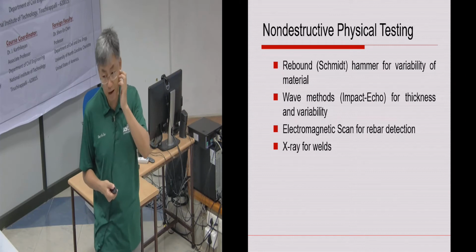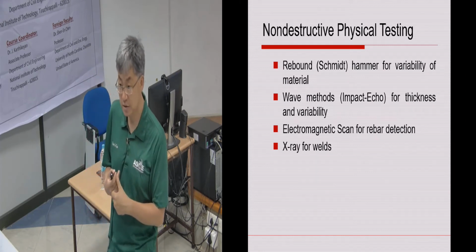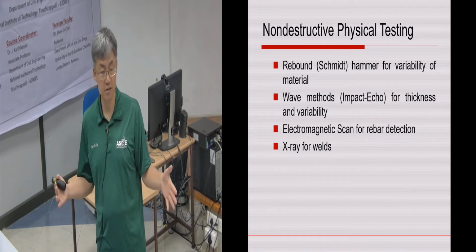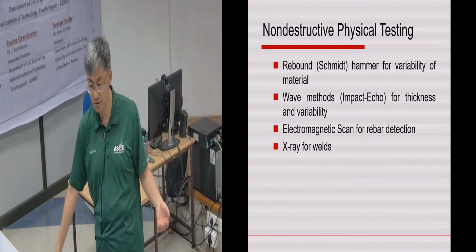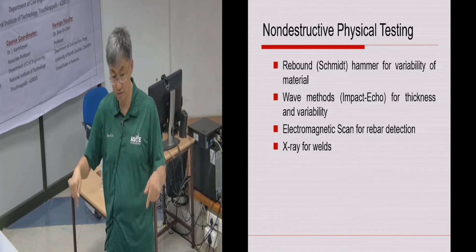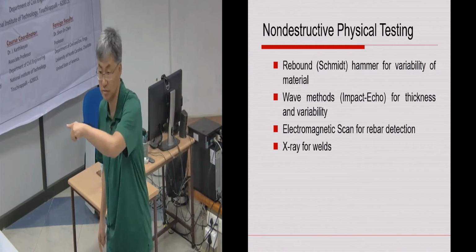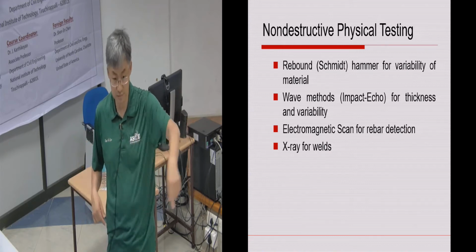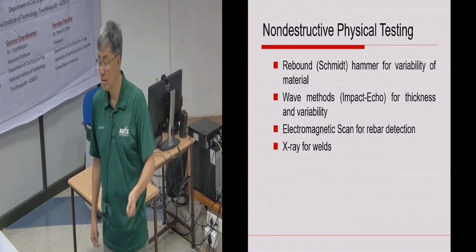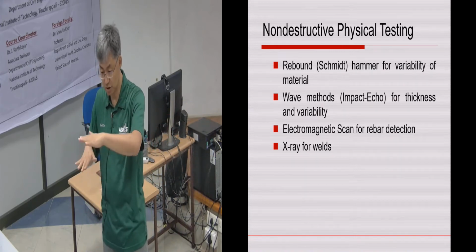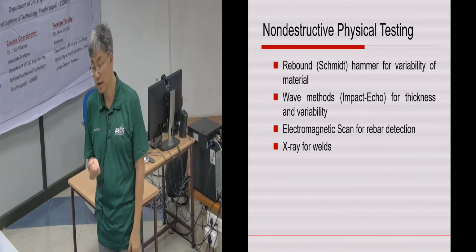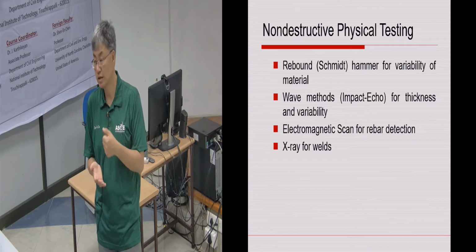Electromagnetic scanning for rebars is getting very common in the US because it's very easy to perform, but it requires a big setup. Okay, so for example, if I wanted to detect and determine how the rebars are distributed on this floor, I have to mark up this ground. So I'm in a way disturbing this area, right? But then you take the scanner and slowly scan. It takes a long time, but it gives you a very nice image of where and how deep the rebars are, and even the size of the rebar. Okay, so this kind of tool is now industry standard.